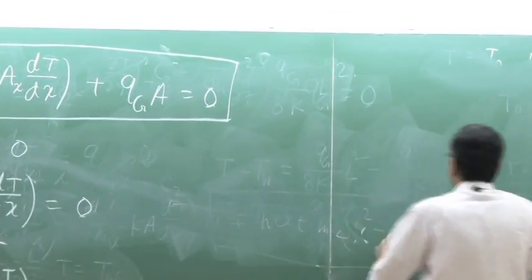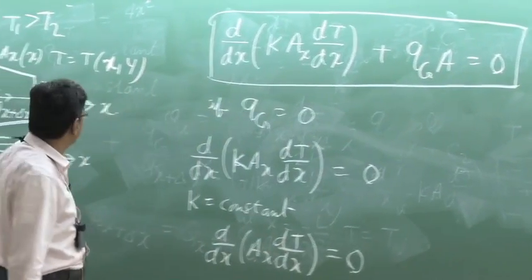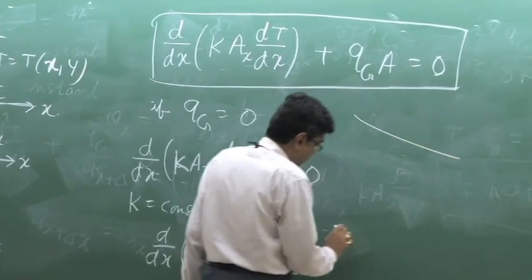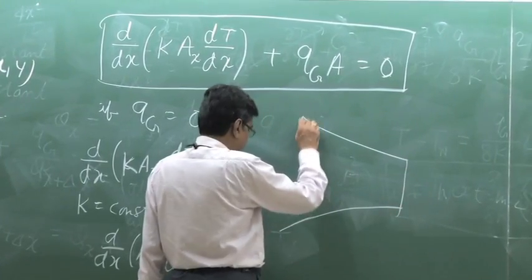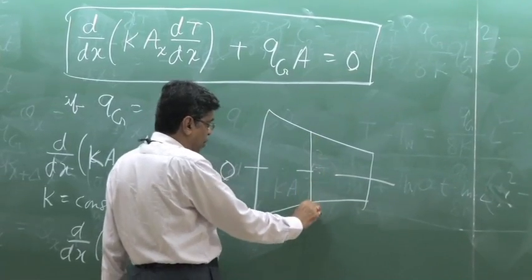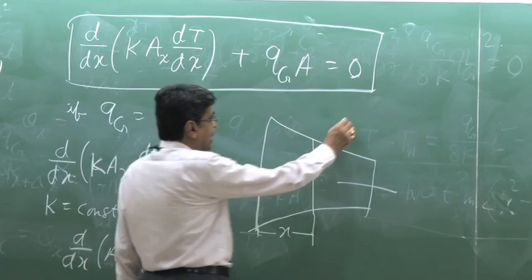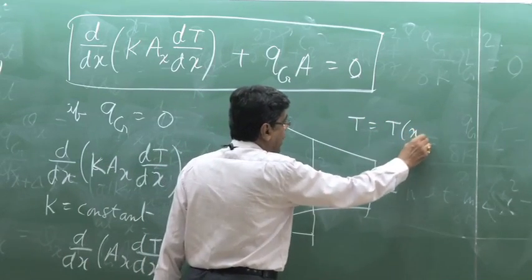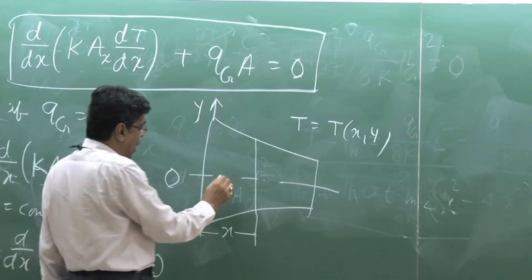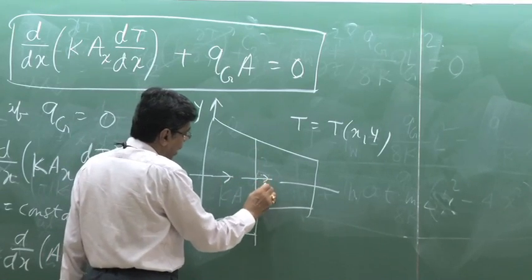This can also be appreciated if we consider the variation with y, how the mean temperature comes into consideration. Let me do it this way, so that you can be satisfied that we have already considered a mean temperature, where from this comes. Let us consider a section at x. Now if we consider that T is a function of x and y, this is an integrated form. Now if I have to find the value of Qx at this section, what is the value of Qx?